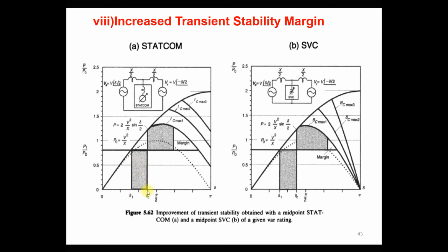When the power system is restored after the fault at angle delta C, the actual power transmission increases, because now delta has increased. As we know, the active power transmission depends upon the voltage as well as the angle delta. So as the angle delta increases, the active power transmission also increases. In steady state condition, active power transmission is P1 at angle delta 1. Clear? But after the fault, delta is increasing from delta 1 to delta C, so the actual power transmission increases.